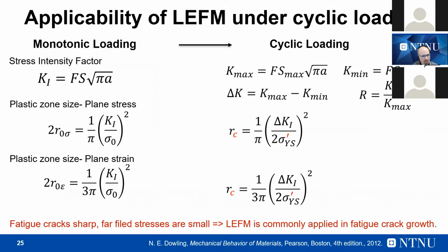And here is the calculation of the cyclic loading. I don't want to go much into the detail. You will have the presentation available later, so I don't think it's important to go inside the details. But what is important is to understand that also under cyclic loading you have a plastic volume that is small, but is present in front of the crack tip. And it is always better to check its size before making any other assumption.